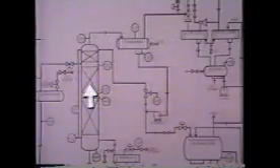When the reflux rate is too low, there isn't enough reflux going back to the column to keep the top of the column cool enough. When the upper part of the column gets too hot, the bottom's product vapors rise too far up the column. These vapors mix with the overhead product vapors, contaminating them. It's easy to see, then, that the reflux rate is important to the proper operation of the distillation column.